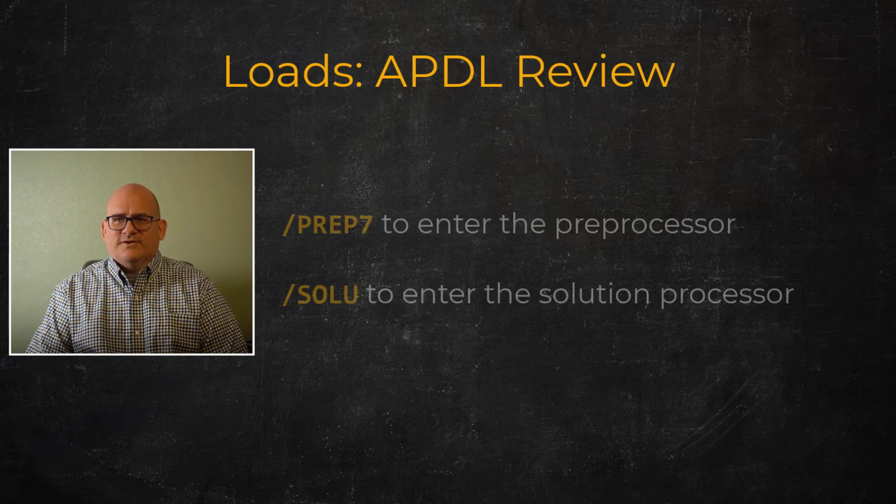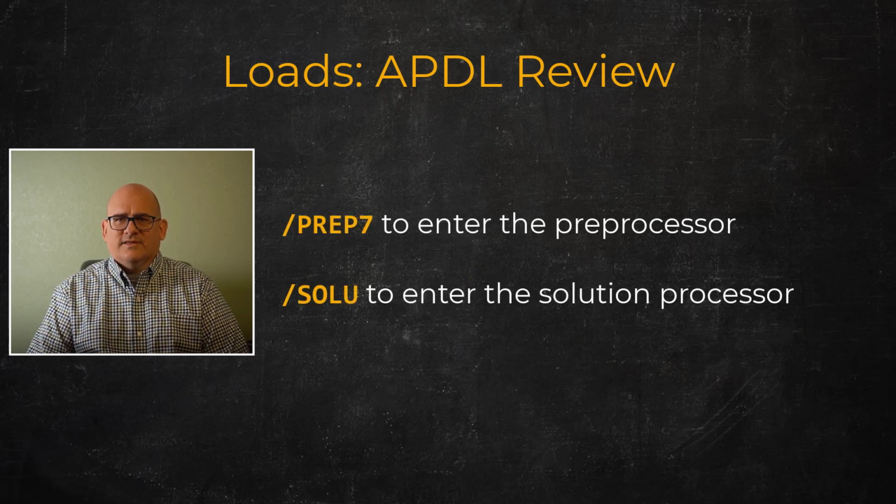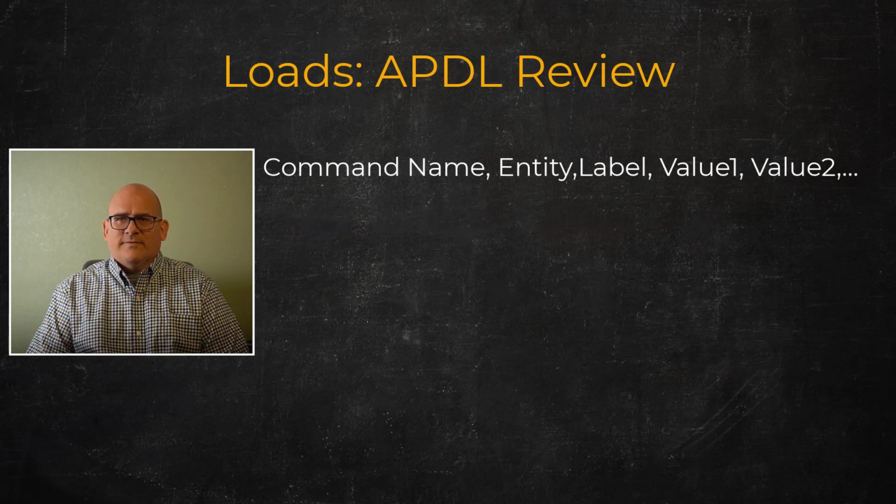Note that commands associated with mechanical APDL loads can be issued in both the preprocessing and the solution processors. Loads can be defined, listed, plotted, deleted, and sometimes even scaled. The typical form of a load command is the command name, entity to which to apply the load, the label of the load, and the values.